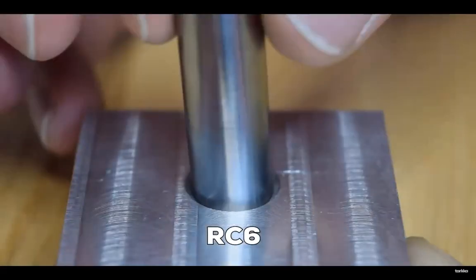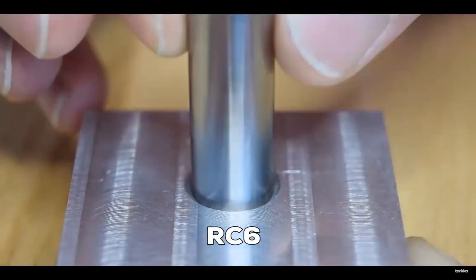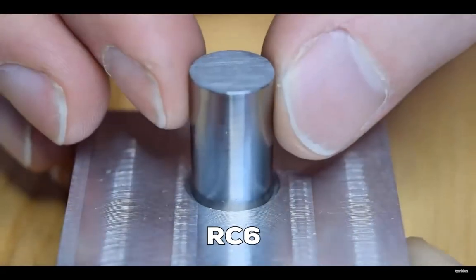The next category of fits is called running fits. A running fit is typically used when you need two parts to mate together freely, that's to say without any force, but you need some degree of precision in their alignment.